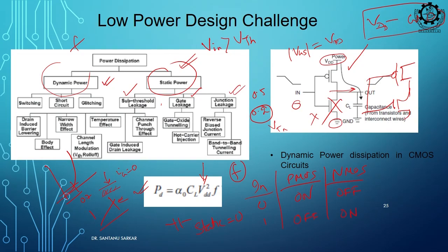Most of the time all the transistors will not be strongly off, right. If you have an NMOS with VDD 1.8 volt and you are giving 0 volt, it is strongly off, right. But if you are reducing the swing, then it is not that strongly off. Okay. This subthreshold leakage will be more predominant.